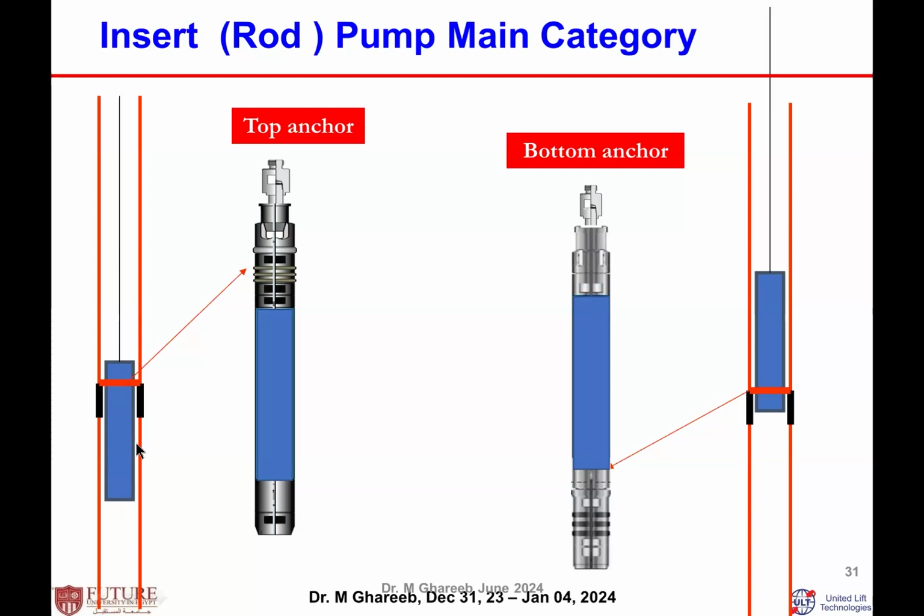What will the pressure be outside the pump barrel? The pressure outside the pump barrel is the pump intake pressure. Usually the rod lift system is used in wells with very low bottom hole flowing pressure, which can be 50 psi, 100 psi, 20 psi, 30 psi. Then you have a big delta P across the barrel in the downstroke, and the barrel can start to have some ballooning effect, and sometimes can even burst.